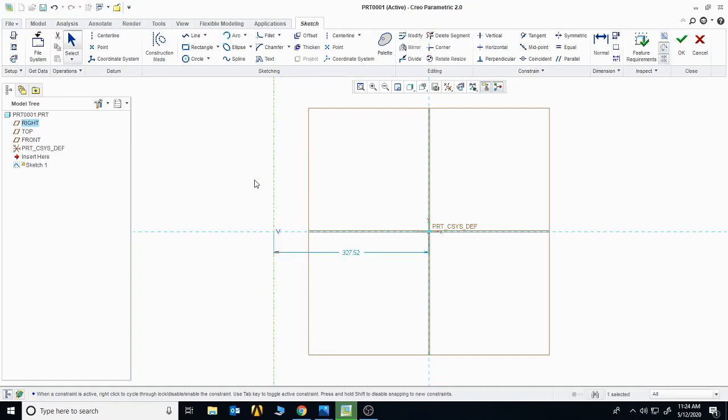The center line is defined so that when you make a spring it will revolve around this. Then you need to define a simple line that will define the length of the spring, or the height of the spring. This will be the length of the spring. You can adjust the dimensions from here. Secondly, the distance from the center line to the line shows the radius of the coil, or the radius of the spring. So you can adjust it from here.